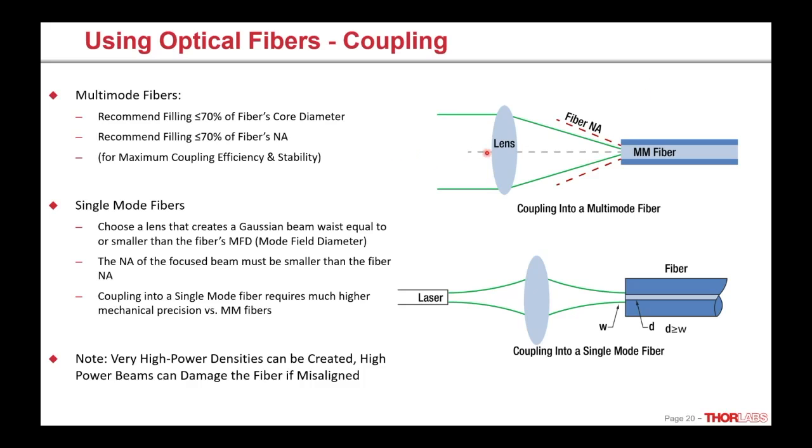And of course, the beam of light, the lens and the fiber need to all be along the same optical axis. And we recommend fixing the lens, having the beam of light be normal to the lens and centered, and then moving the fiber linearly in X, Y, and Z to bring the end facet right to the point where the light is focused.